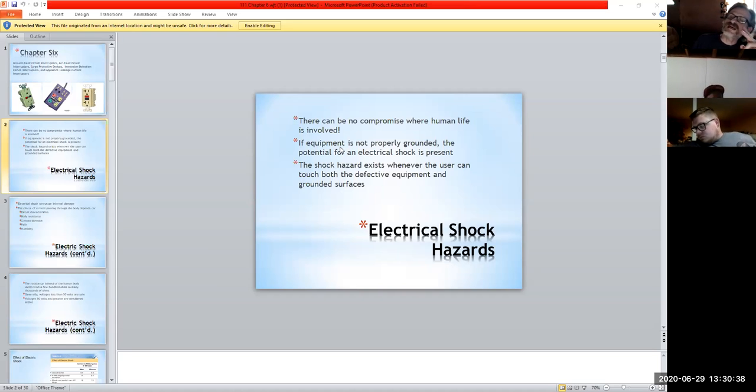Whereas the AFCI is looking for little ripples in current change, and then it'll trip. So it's really a matter of how the electricity behaves. It would probably be a good thing if all of your receptacle breakers throughout your panel were AFCI backed up, believe it or not.